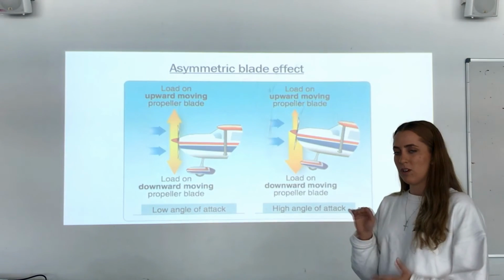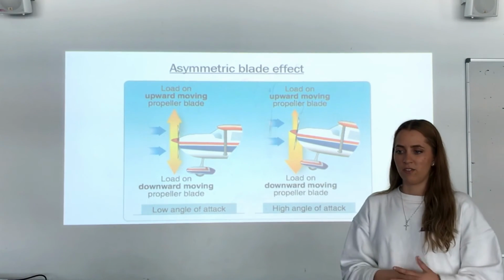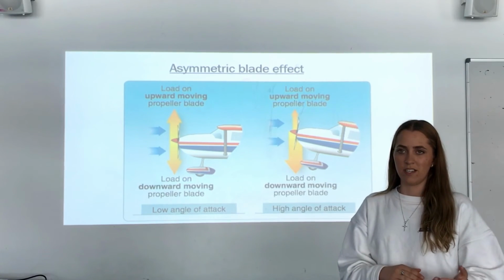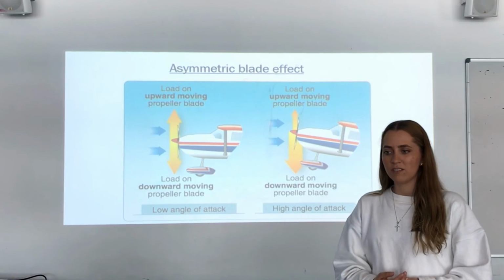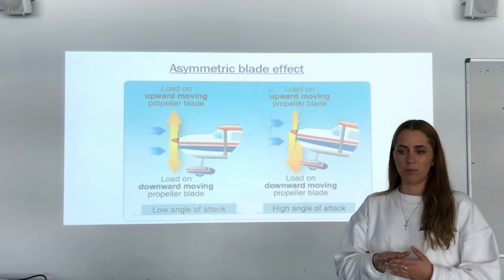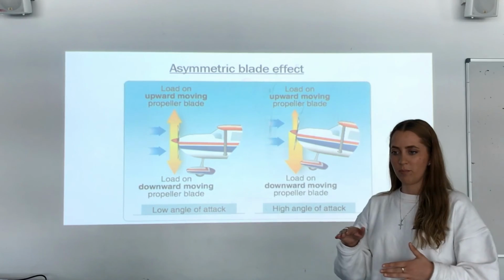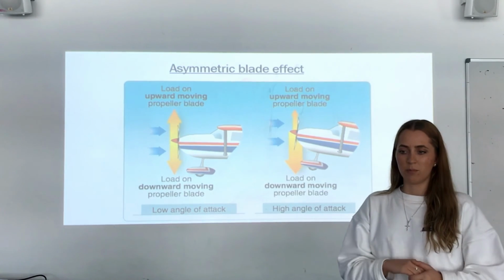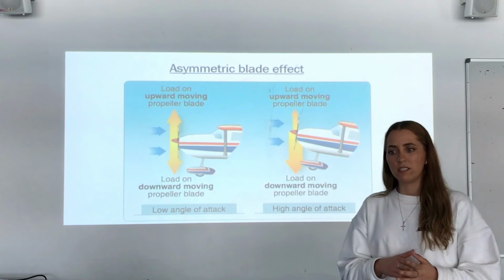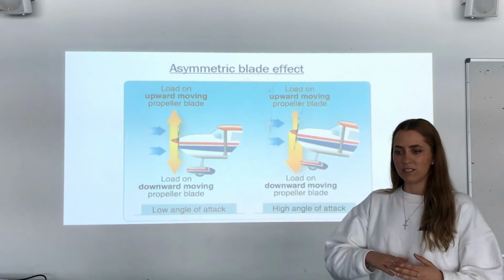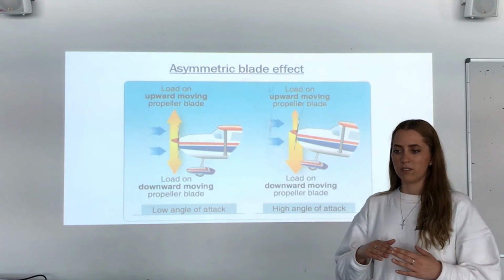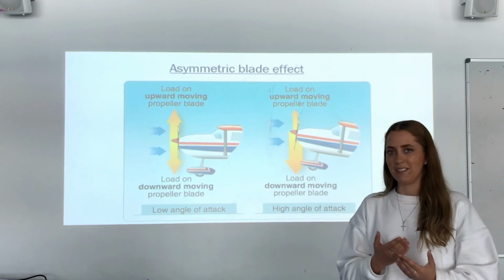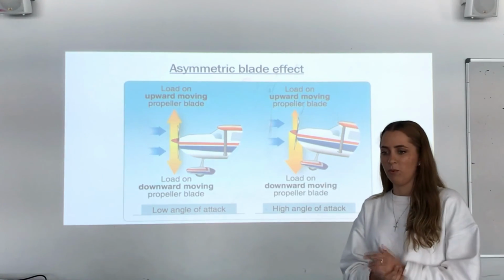When the aircraft is moving horizontally, so forward, the direction of the airflow is different on each side of the propeller disc. During the takeoff run of a tailwheel aircraft, while the tail is still on the ground and the propeller shaft is inclined upwards, the plane of rotation of the propeller is tilted rearward. Because this only takes place when the propeller disc is inclined to the relative airflow, once the pilot lifts the tail, the disc will be closer to a right angle to the relative airflow, the thrust line will move back to the centre of the disc, and the yawing moment will be reduced.